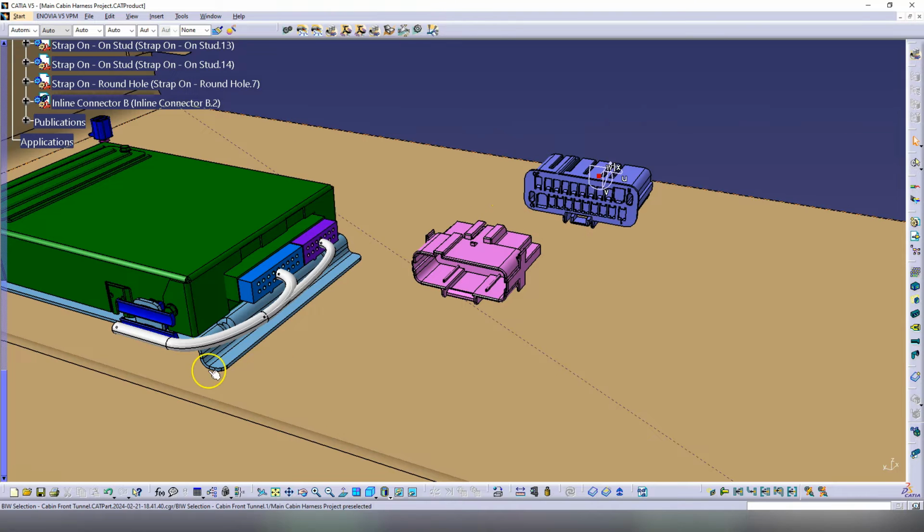So I don't have the seat here because we don't really need that, but I have a specific project in the course where we deal only with the branch that goes from here to the seat connector, and I also have the seat here in all the positions, and I show you how to do that dynamic move, how to calculate that. And basically that's one of the most difficult pieces of dynamic harness that you have to do inside the vehicle, because many times the space is really tight here, so I show you a lot of tricks in there.